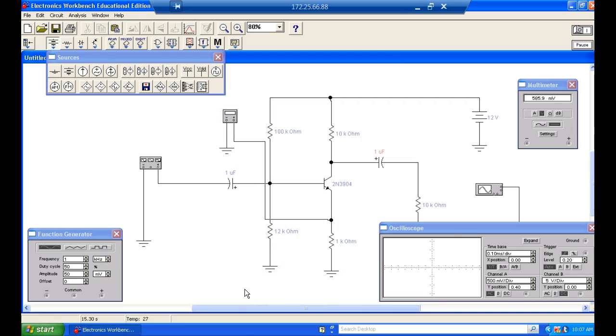There we go. So this is where it's supposed to be, right? You understand that? So that guy's okay. So we know this guy's conducting what it needs to be. This guy right here is low. So there's only one thing that could cause that. Either this resistor's gone up in value, right? You understand, or the current's gone up. Are you okay?